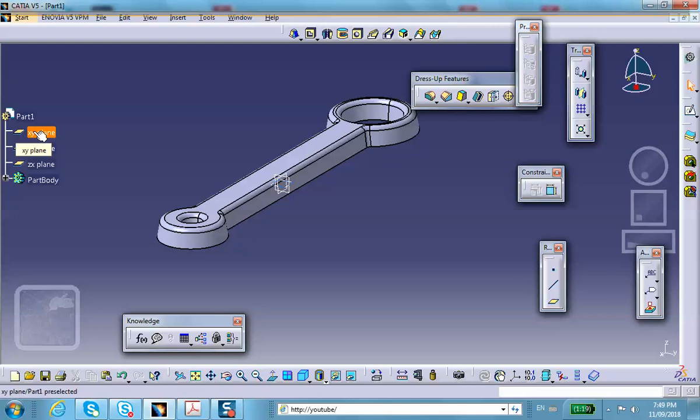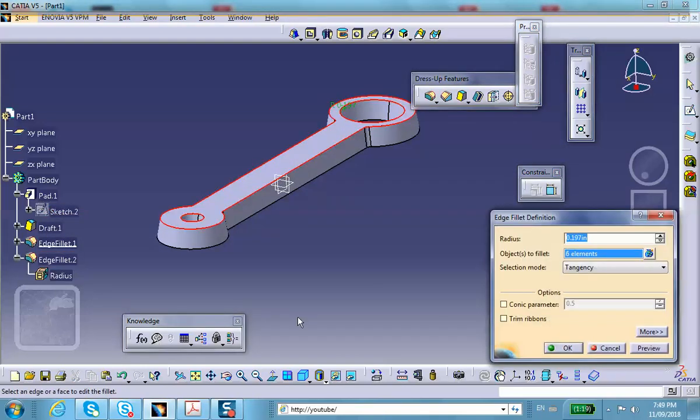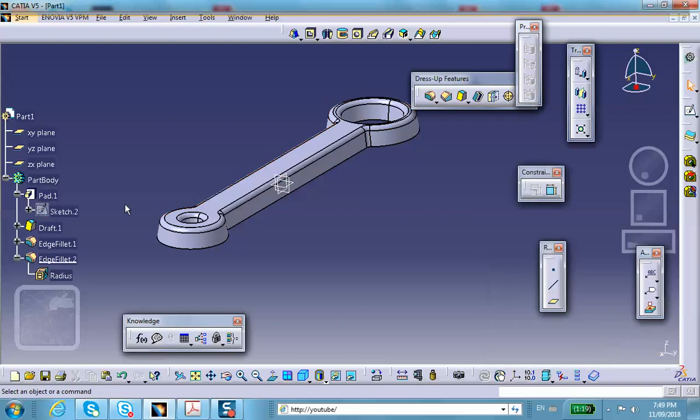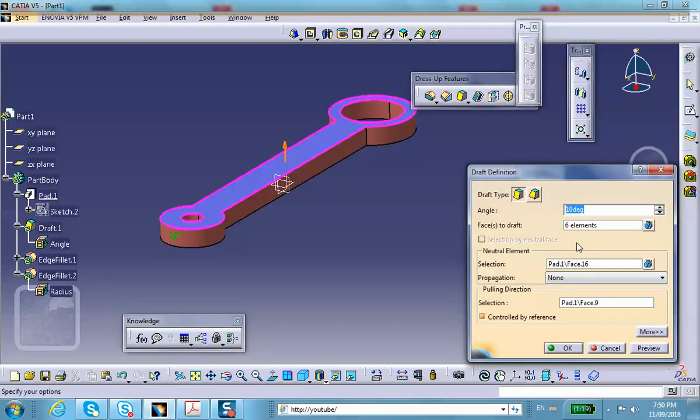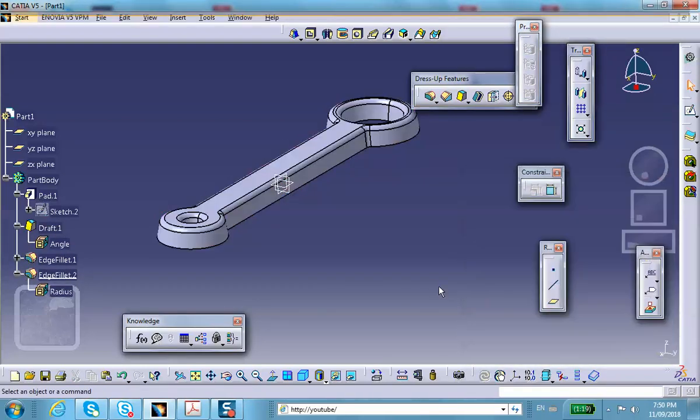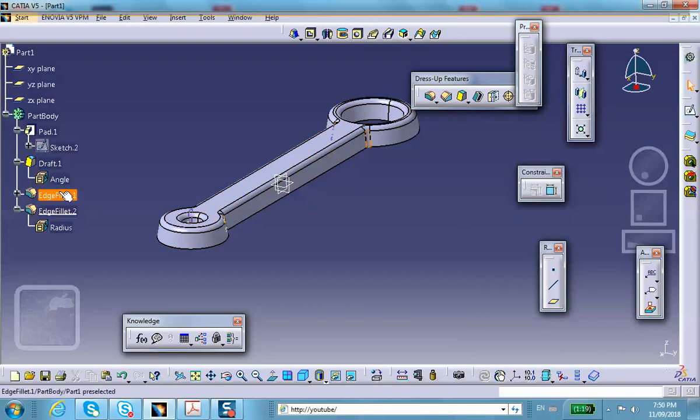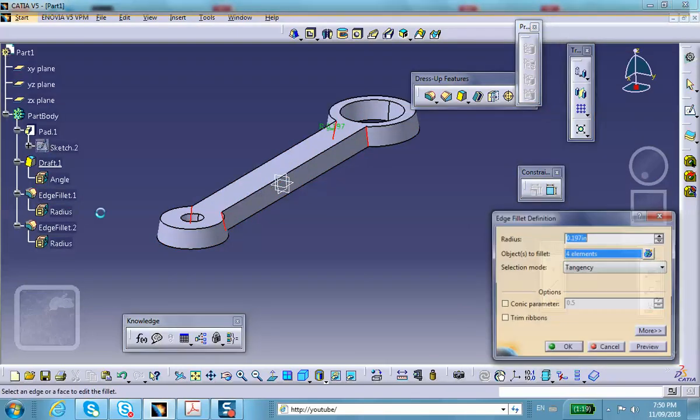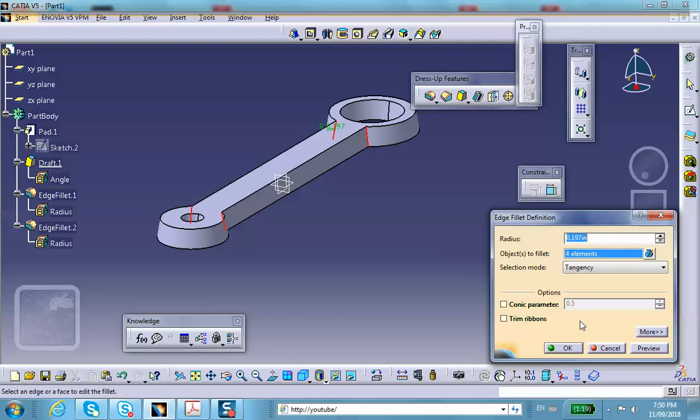Any of these things that you don't like, the fillet radius and things like that, you can always change. So double click on this thing. Actually, when you notice that when you do that drafted pad, it creates some edge fillets, but these things could have been changed, either initially or right here you can go and change it. For example, you can go directly here and change those fillets to whatever you want, the radius. I'll let you play with it.